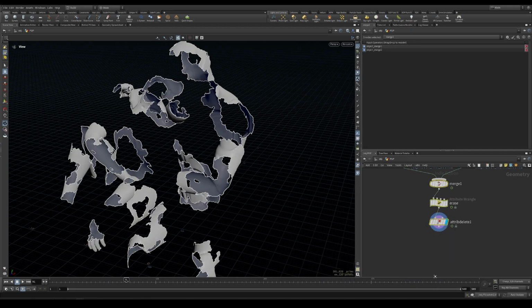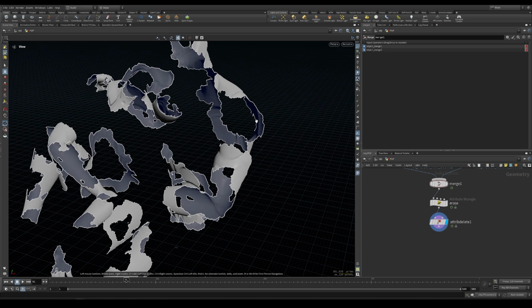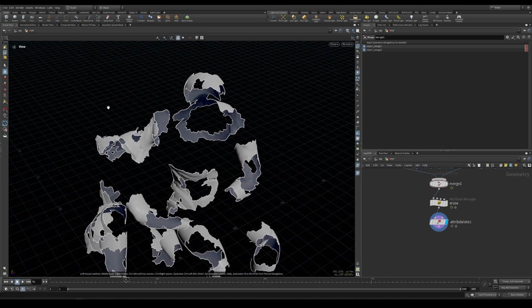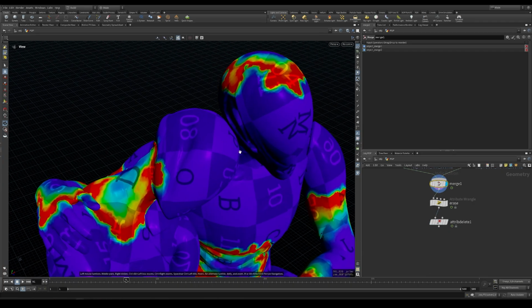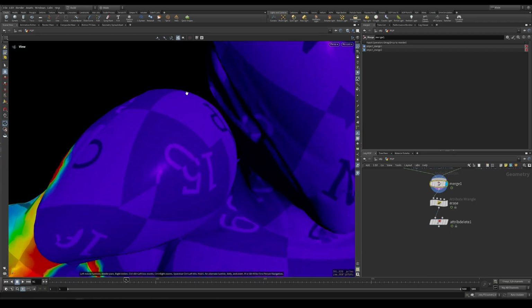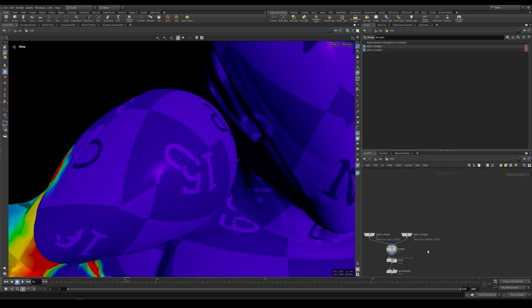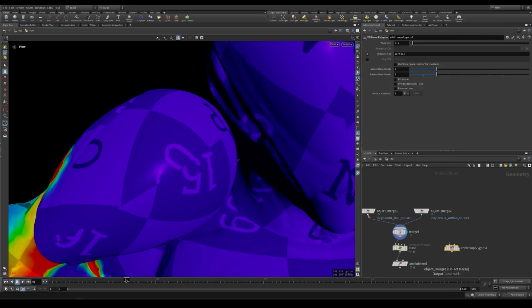And finally, since the particles will be emitted with some force that will push out of the mesh, we could have some problems in the areas where the two meshes are touching each other. So before caching out for the particle simulation, I want to take a VDB from polygon for both of the meshes.